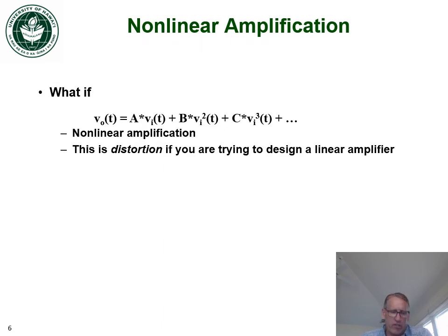All right, how do we describe nonlinear amplification? In practice, all amplifiers are nonlinear. Sometimes the nonlinearity is small enough that we can ignore it. It depends on the application. But typically, if we have nonlinear amplification, it's described by a power series.